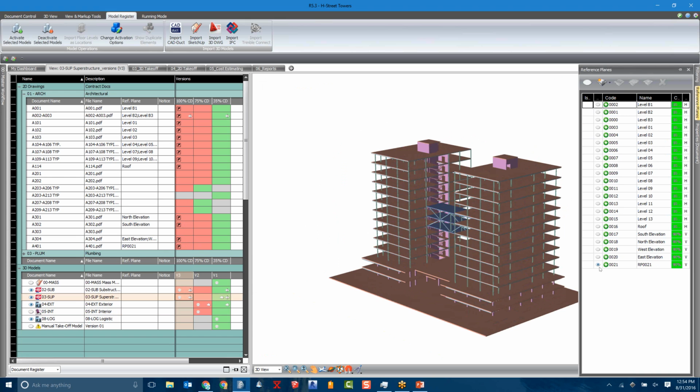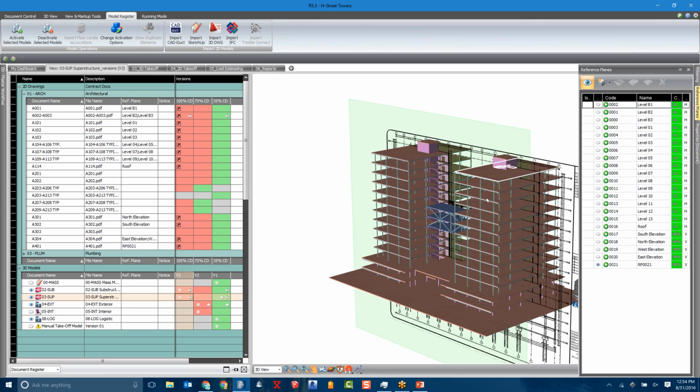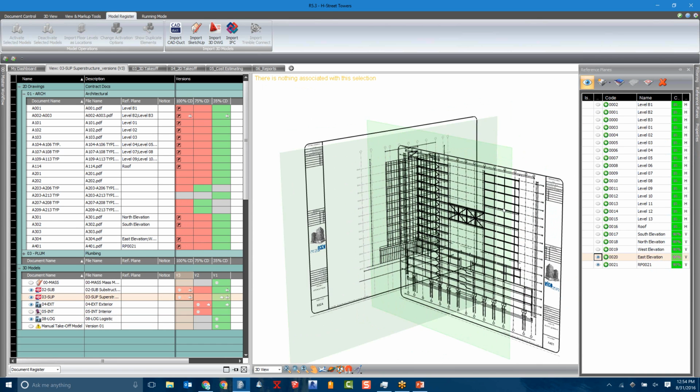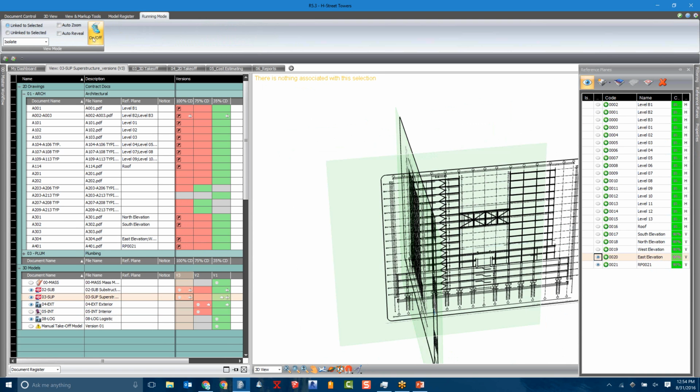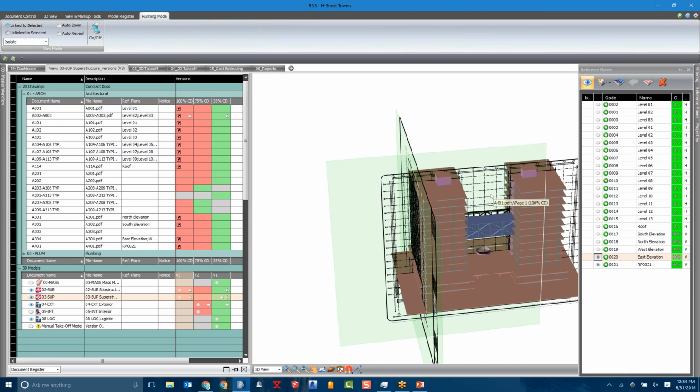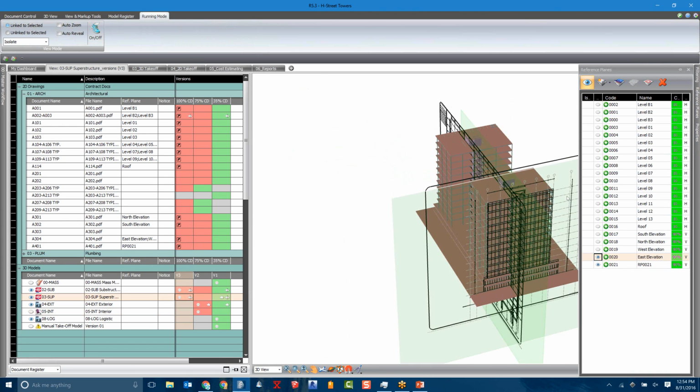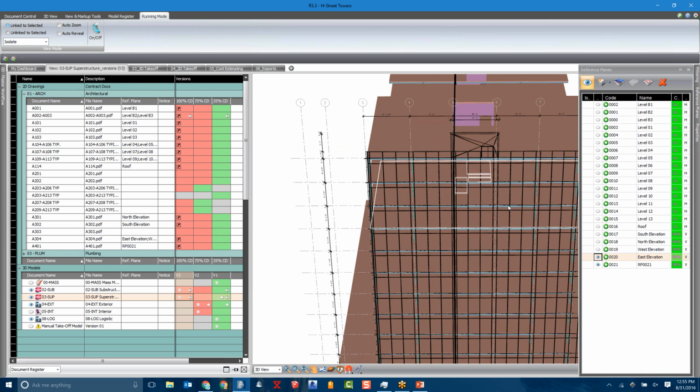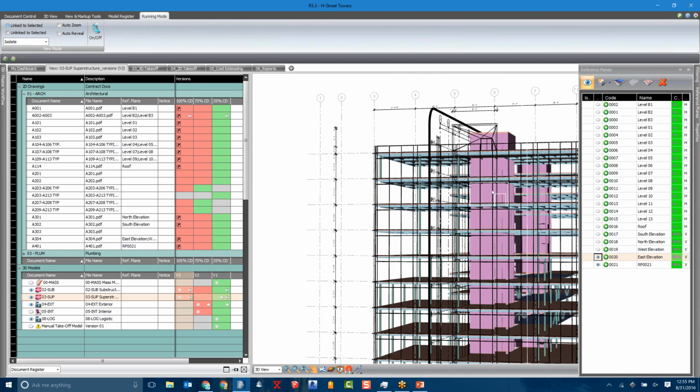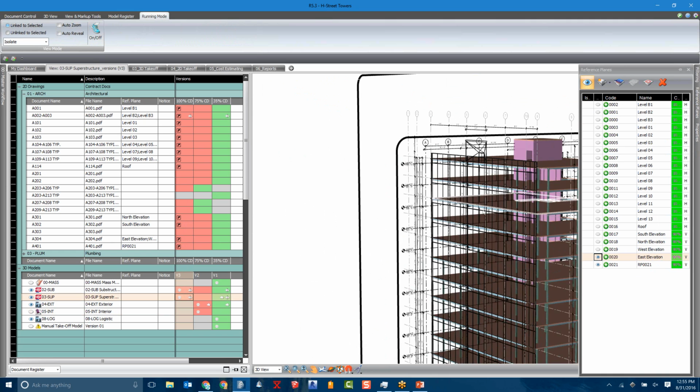Now we're able to basically work in a hybrid mode. So for example, what that means, I can reference and map a 2D drawing to my model. So in this particular case, I've mapped a section drawing to my model. I can also map an elevation drawing and understand what changes have taken place, or how does the model stack up to the drawing, and understand with confidence, say, hey, this particular drawing is perfectly matched up with my superstructure drawing.